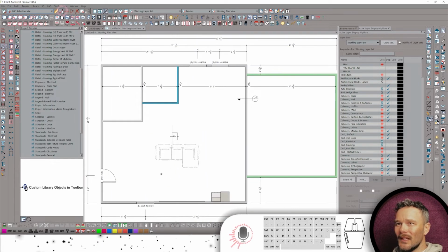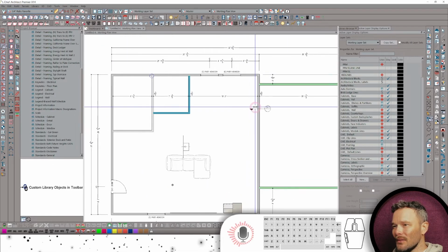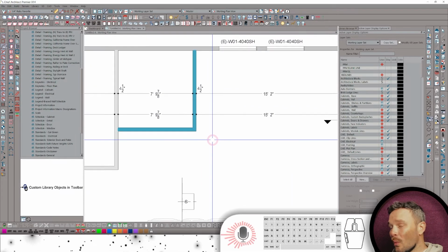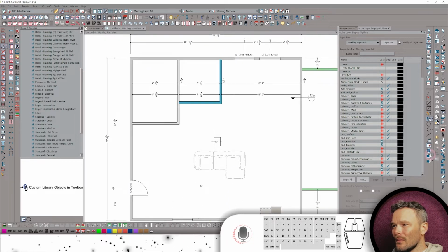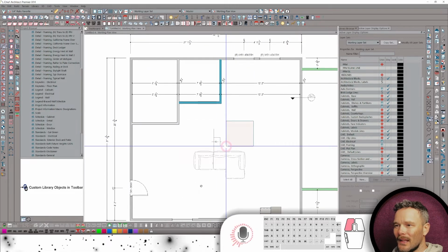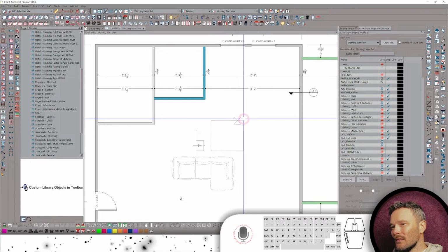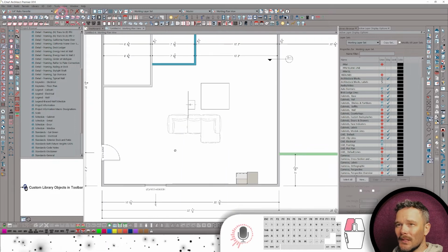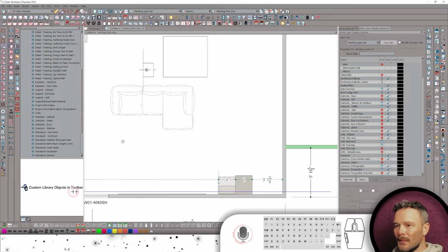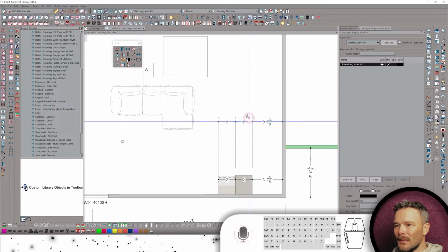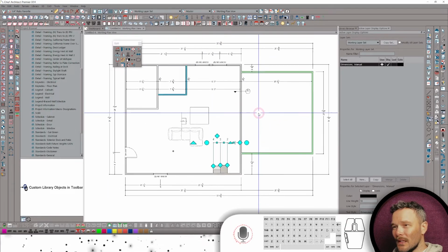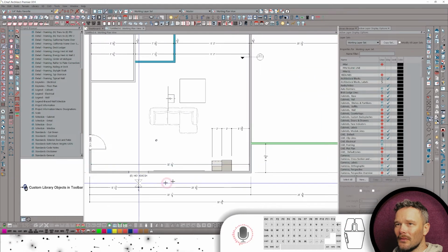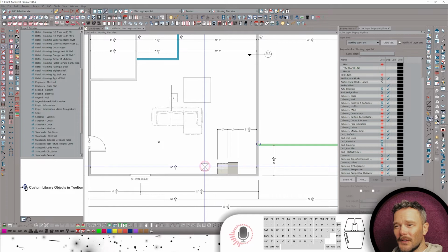So if we switch to an interior dimension side, there's a couple notes on what exactly the differences are. You're going to see here, we're not showing our wall widths when we use this. The other thing that will show up in the end-to-end dimension tools, we can dimension to these polyline solids. And also with the interior dimension tool, this will dimension cabinets if you need to. So we do get cabinet dimensioning with that interior dimensioning default versus the manual dimension tool, which will not dimension cabinets.